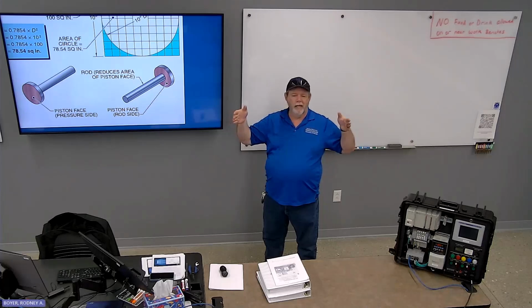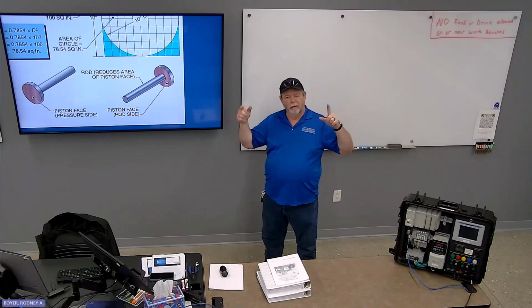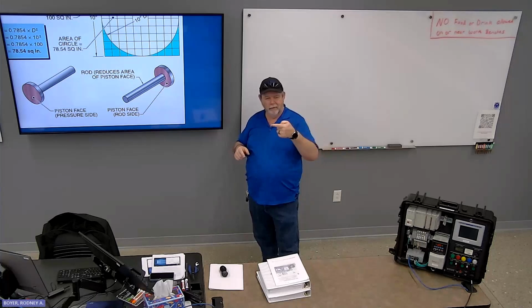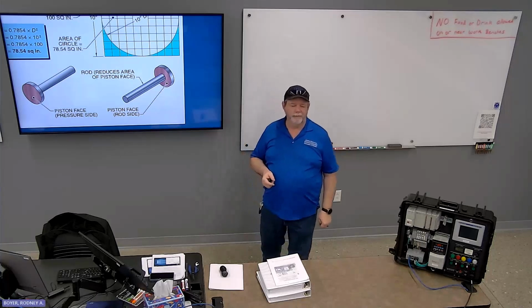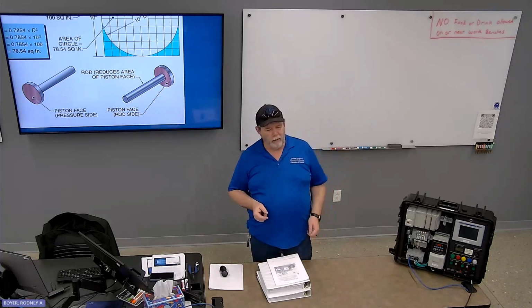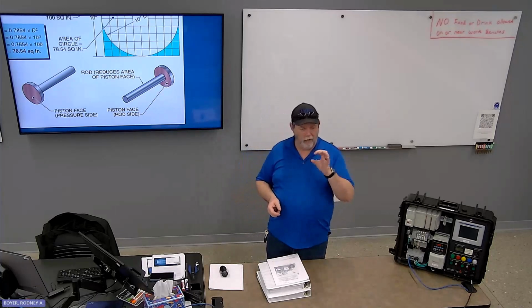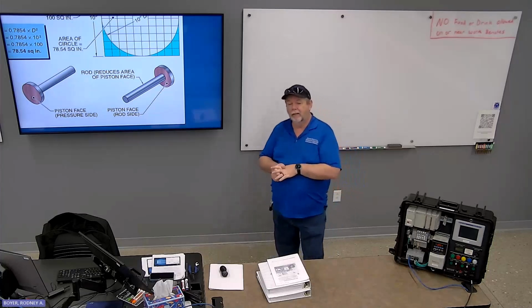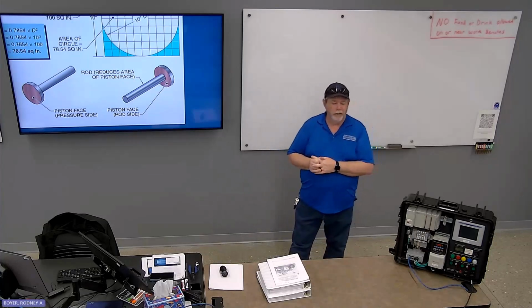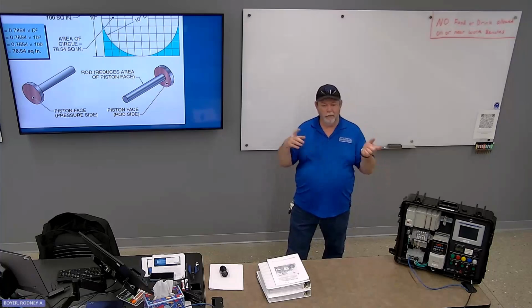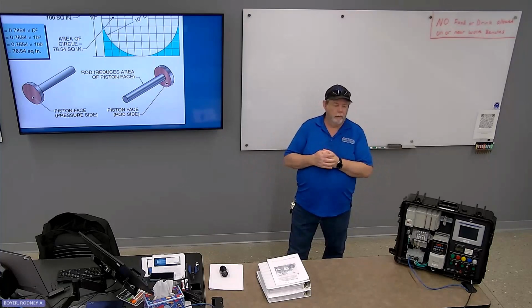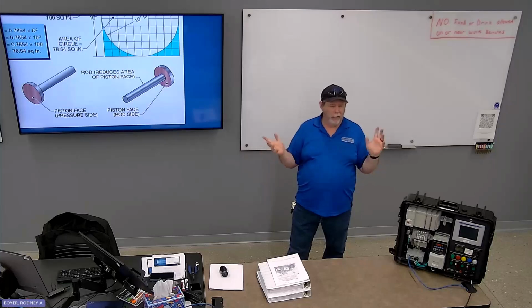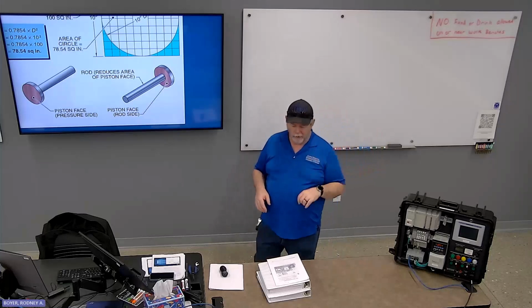People will invariably say it doesn't move anywhere because you get equal pressure on both sides. But it will move slowly to extend the rod, simply because you have whatever diameter the rod is, less surface area on that side than you do on the side that doesn't have a rod. More area equals more force equals movement. Assuming you have enough to overcome friction, but we're going to assume zero friction in that case.